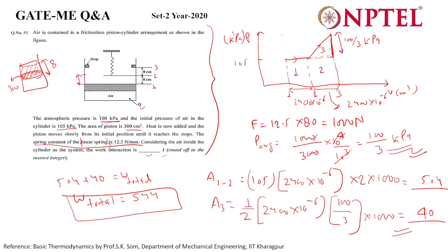Actually, this is given just for reference. They are saying that if the internal pressure is more than this, it will go up. That's why there is no use of that. Because I haven't shown you the force balance here; I directly wrote these equations. Why does this equation come from the force balance? Because we take P into A, and from the bottom side it gets cancelled.